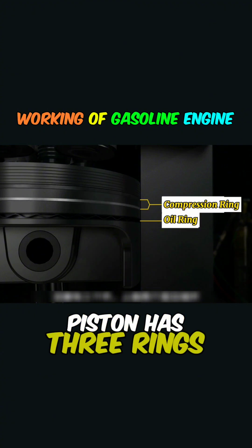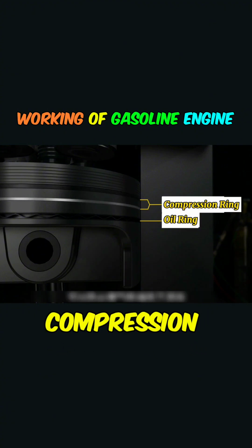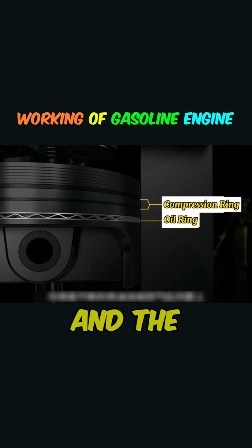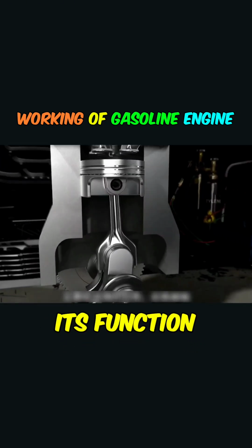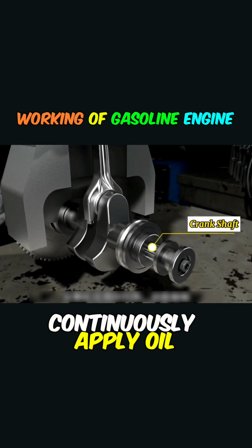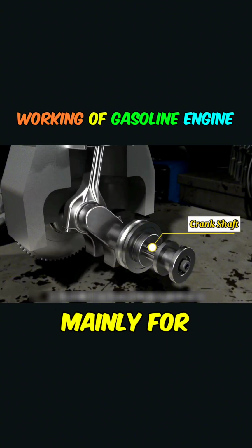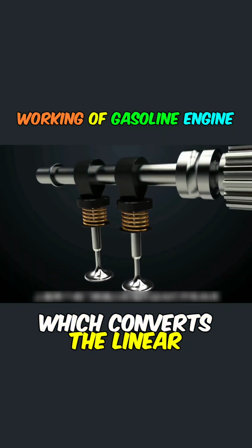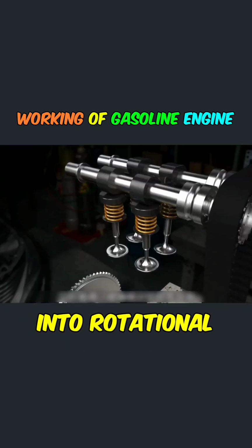The piston has 3 rings. The upper 2 are compression rings, which prevent flue gas and oil from flowing downward, and the lower one is an oil ring. Its function is to continuously apply oil to the inner wall of the cylinder, mainly for lubrication. Above it is the crankshaft, which converts the linear motion of the piston into rotational motion.